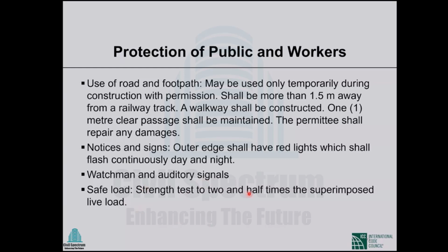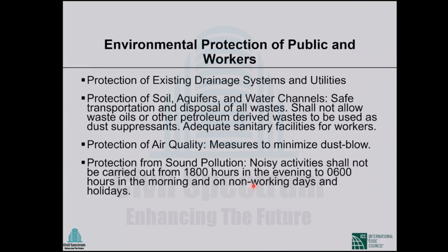Safe load, strength test: in places where you have a platform on top of a walkway, you should conduct a strength test of that platform. Things like that. Environmental protection of public and workers. Protection of existing drainage system and utilities. This is very important.